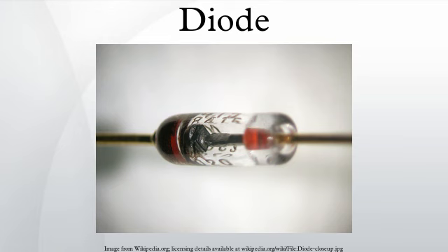Most diodes therefore have a negative temperature coefficient, typically minus 2 mV per degree Celsius for silicon diodes at room temperature. This is approximately linear for temperatures above about 20 kelvins. Some graphs are given for 1N400X series, and CY7 cryogenic temperature sensor.